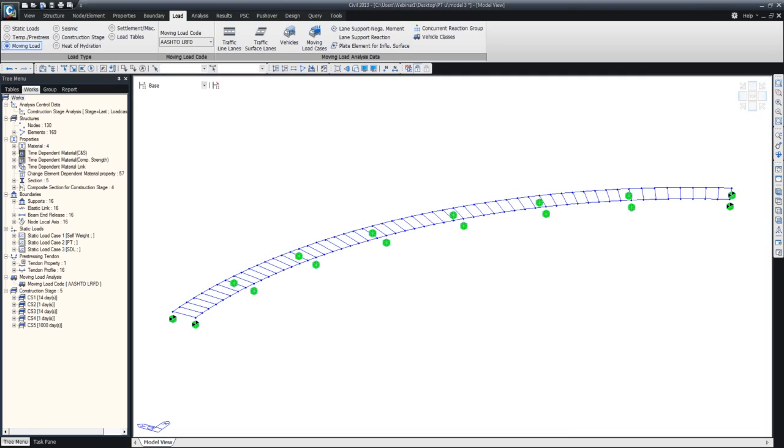Now sometimes engineers want to let the rest of the curing occur while the segment is already in place. So you can define the age as 14 days and let the structure stay as it is for the first stage with a duration of 14. So that makes up for 28. I hope that answers your question.